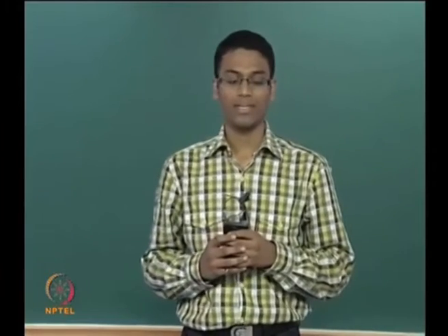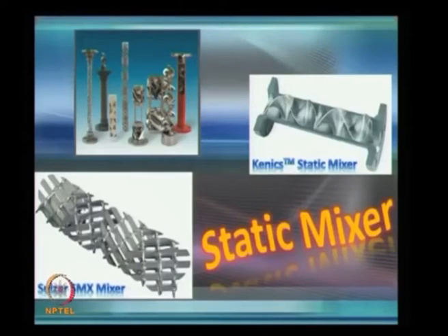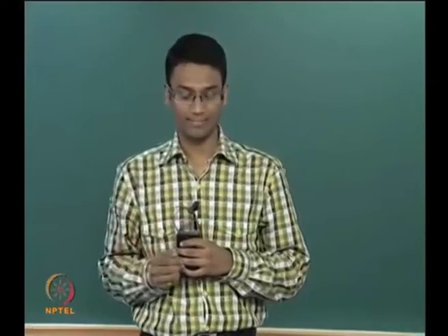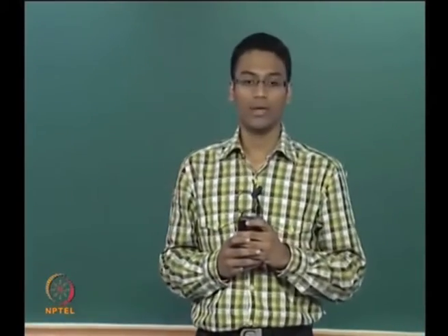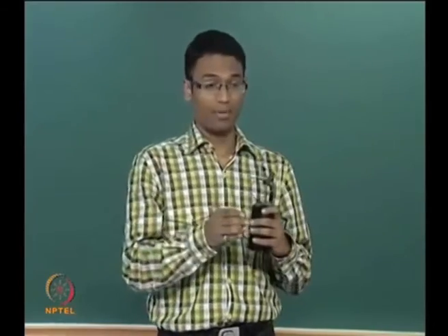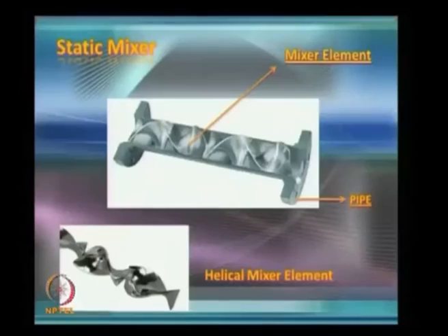CH10B008. Today I will talk about static mixer. A static mixer is a device which mixes a fluid flow homogeneously. As its name suggests, this device works statically. Therefore, it does not require energy except for passing the fluid through the static element. As you can see in this figure, the static mixer is fixed in a pipe.